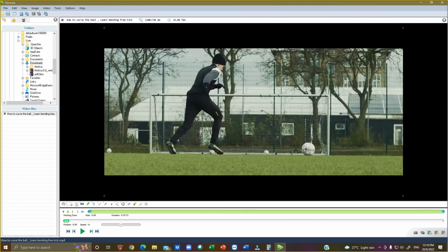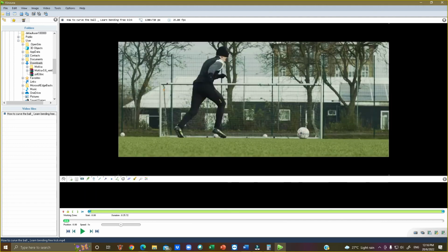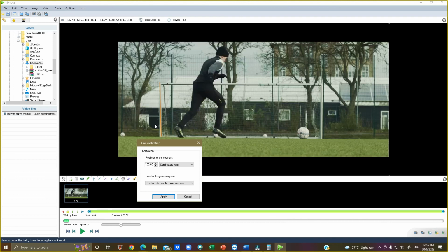Because when we use Kinovea, first we need to do calibration. For example, like this. What we want to calibrate is the length, because Kinovea is very sensitive to length. So you need a video whose plane doesn't change, and then you know the length. For example, the football goal post, how high is it? Example, somebody who plays soccer, how high is this goal post? How high is it?